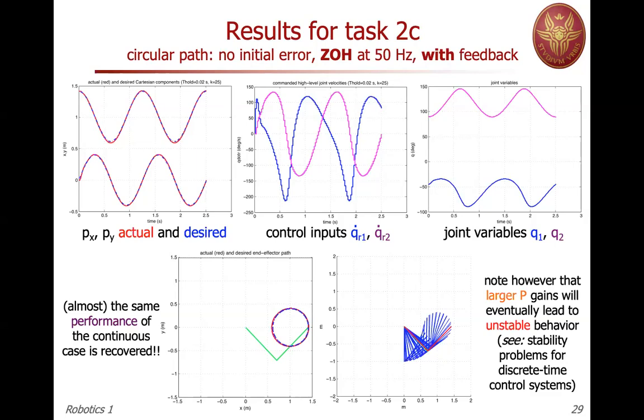We have written that the error E dot is equal to minus k times kp times E, or in the Cartesian space it is the same. This is an exponential behavior, but assuming that everything works continuously. If I replace this with a discrete time version, I can see that even if I'm coming from a system that in continuous time would have been asymptotically stable, in particular exponentially stable, I may hit an instability in discrete time. And this depends on the time delay and on the gain.